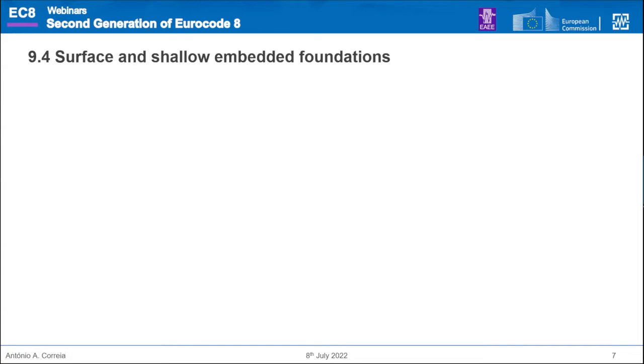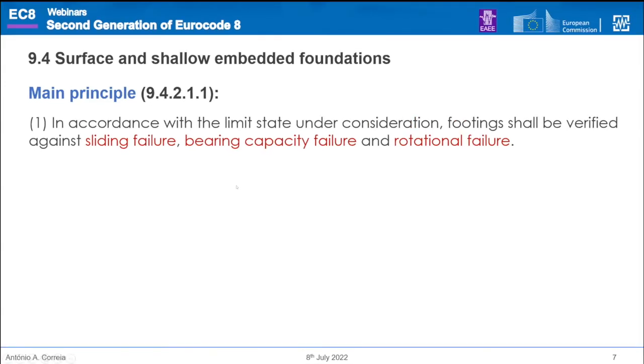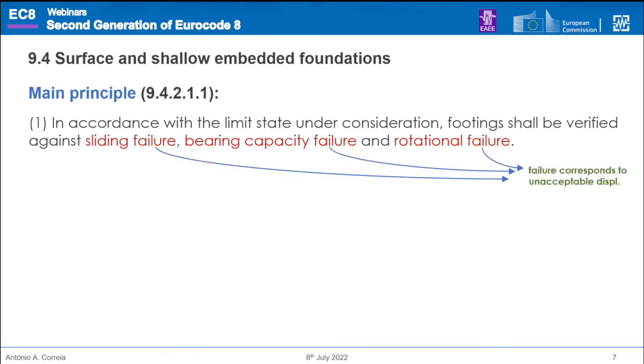Now, regarding the design and verifications of surface and shallow embedded foundations, the main principle in there is that the footings and these foundation elements should be verified against sliding failure, bearing capacity failure, and rotational failure, where failure corresponds to having unacceptable permanent displacements.